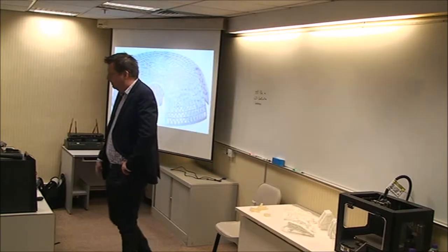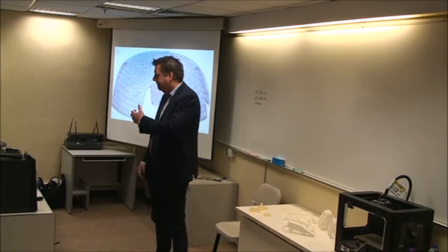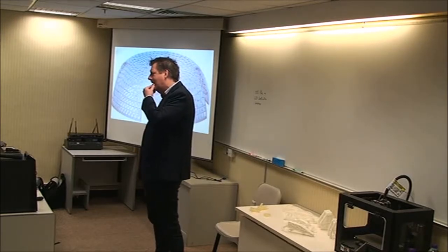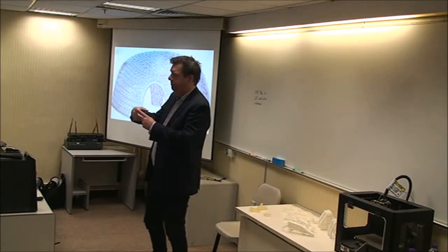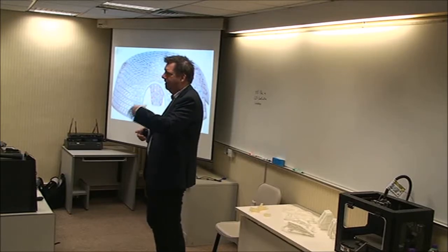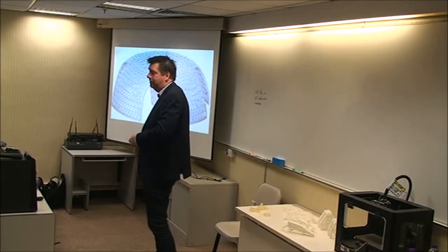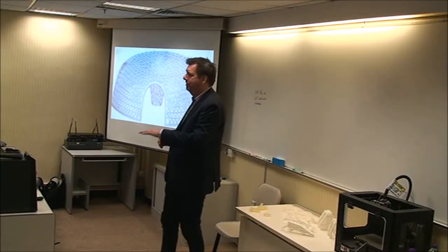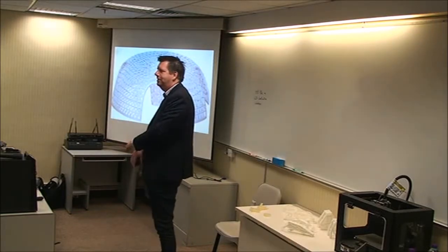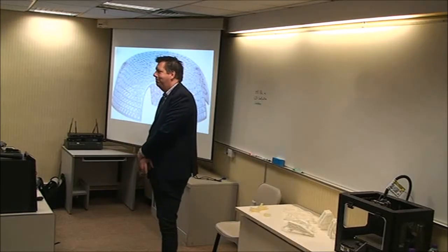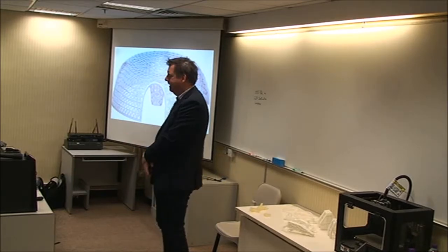Luca is always hassling me with running architectural models on all the latest functionality we have. So I ran that through the lattice approach the other day. Now I know some of these architectural things where you get the structural members come together in all the different nodes, and if you've got these very curvy buildings, you might have 5,000 different nodes in the building, and every one has a slightly different geometry. So again, that lends itself to 3D printing. It also lends itself to the voxel jet type approach where you print the sand to then cast all your individual nodes. So you get something like this. Every joint in that could be different. It's different thickness beams coming in, but in the past you couldn't even conceive of manufacturing it, whereas with 3D printing it does become possible.